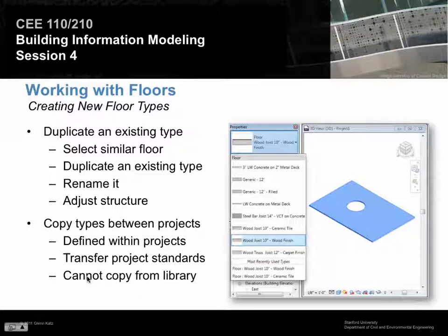Okay. Things like components, doors and windows and pieces of furniture which are loaded out of a library, you can just save as, and then we can load them into the other project. So they're just changed as files. You save a file, you load the file into the other project. Okay, and that works out really, really well because we can all use the CE1110 library, put it out on a file server, we could all share those parts. It's really, really easy when things are these component families.